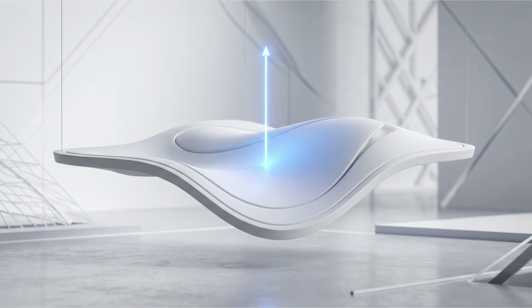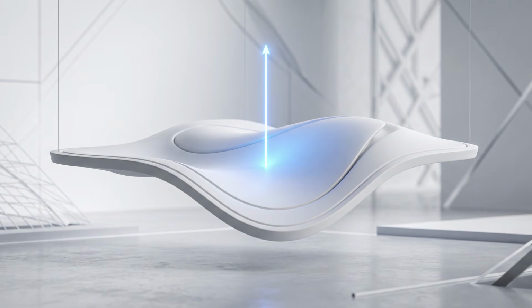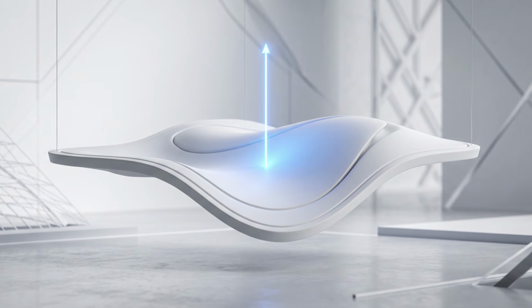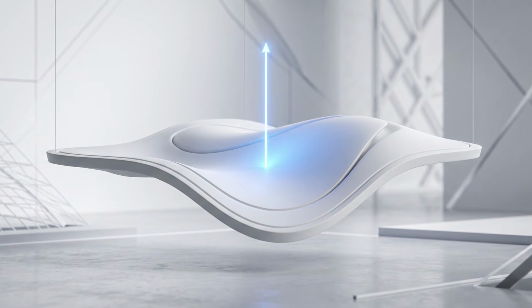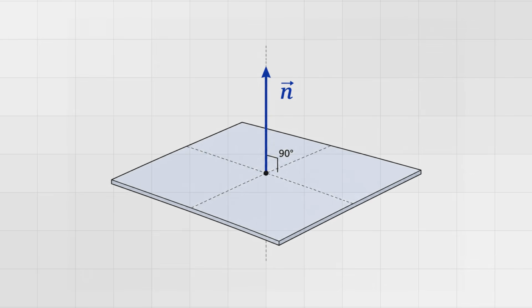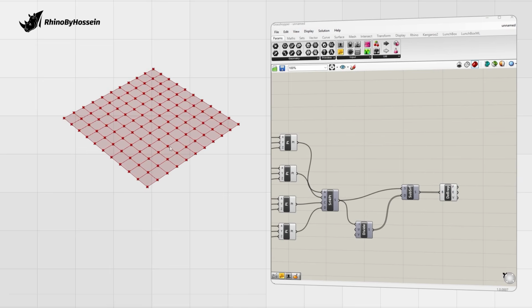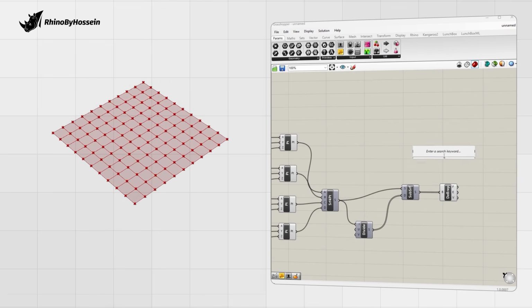Now we arrive at one of the most important parts of the algorithm. To build a space frame, we first need to know which direction each panel is facing. This is where the normal vector comes in. Simply put, a normal vector is a vector that is perpendicular to a surface. It tells us the orientation of that surface. If we want to extend a new structural member upward from each panel, the normal vector gives us exactly the